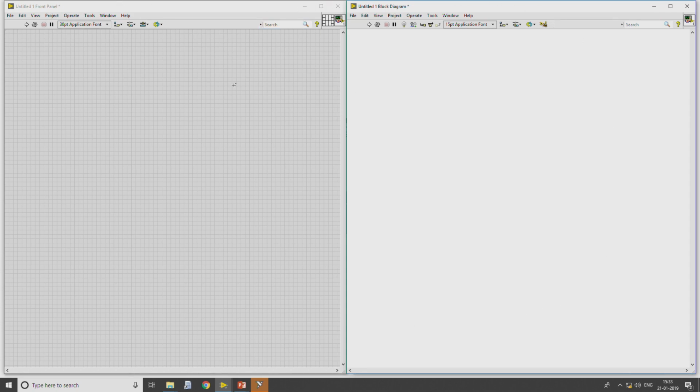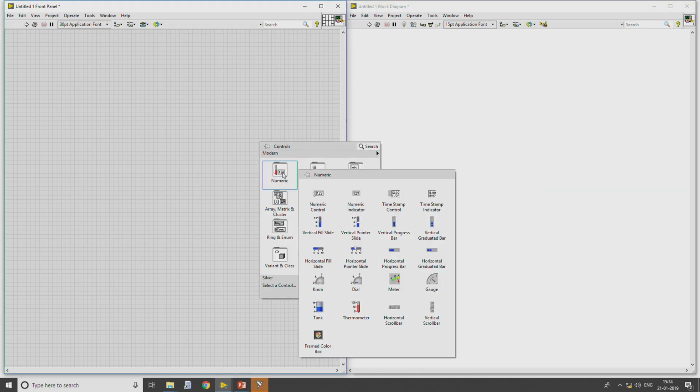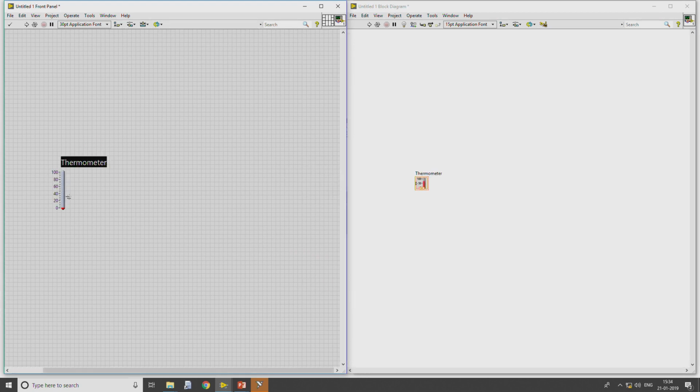Now what we require is to connect our controller unit, one is the error detector and the other is the controller, in the LabVIEW environment, and then interface it to the real world. As our application is similar to a temperature monitoring application, I will take one input, the set point. I will rename it as set point.